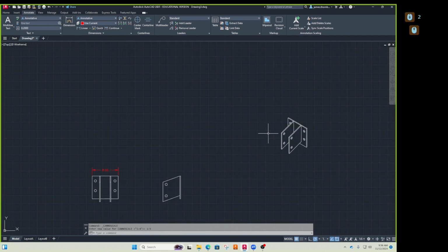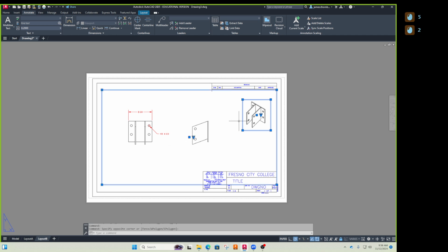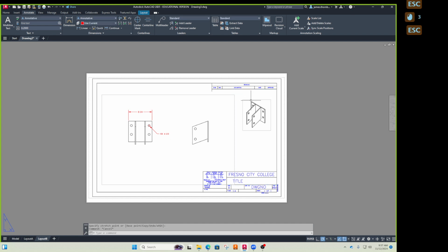So the isometric is still drawn at the same size, and in the viewport I just make another viewport. Like here, I've got one viewport for this stuff, and one viewport for that. And usually we don't dimension isometrics. I am going to show you how in the isometric module, but usually we don't. Usually we do it for making assignments. That's the only time I ever do it. But sometimes if you're showing something to someone that doesn't know how to read prints, then you might dimension isometric because it's a little easier to see, but not for the actual shop drawings. More of a presentation kind of thing.